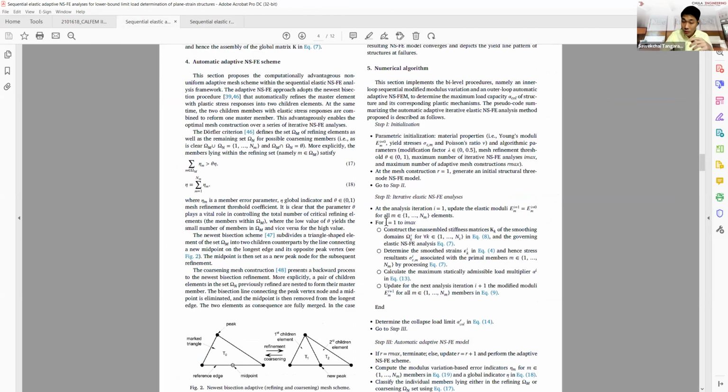The element that I propose is in the active area, where you have a huge intensity of stresses, a huge value and huge variation in the changes of the stresses in some small areas. It requires a lot of mesh in those areas, but where you have uniform stress, it doesn't require the mesh.